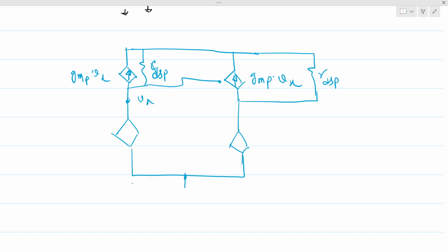So here we have small signal V in, right? So this current is going downward. This will be nothing but 0 volt, this is 0 volt, and this current is GMN times... What do you think? What is the VGS here? So VGS is nothing but minus V in.